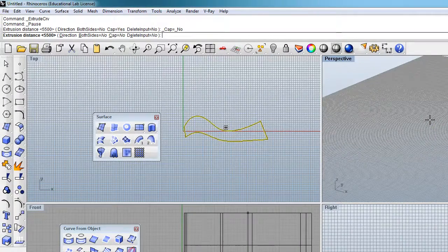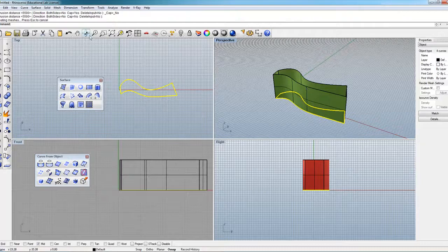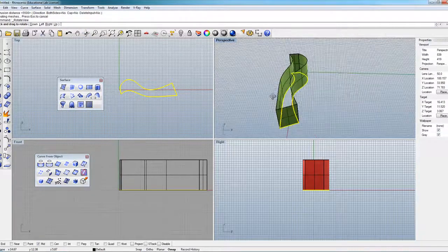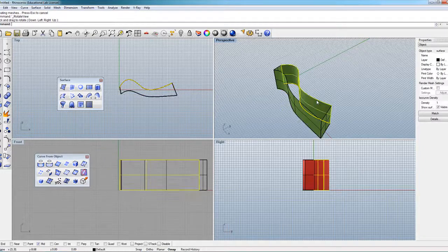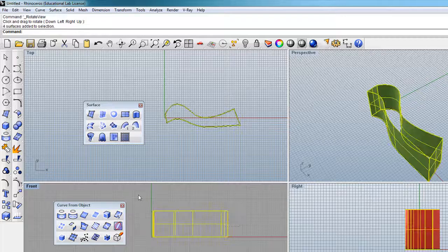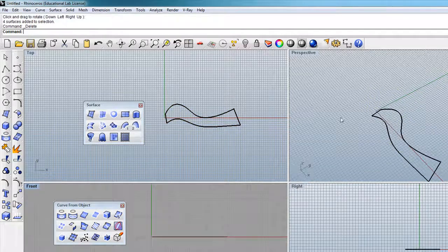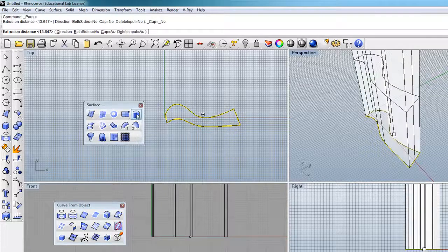As I extrude, there's one more thing that I'd like to point out to you, a selection called cap. Because when we extrude without changing anything, we end up with some kind of four walls, but it's not a solid. So that's not really what we want. So I delete that. I'll do another extrusion, which I will use the cap.